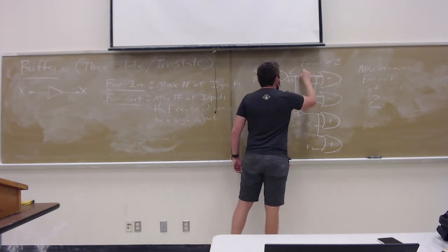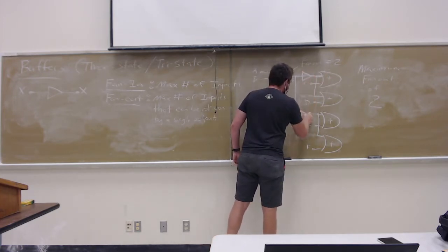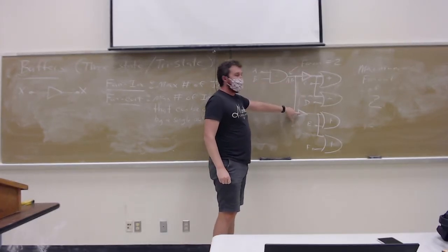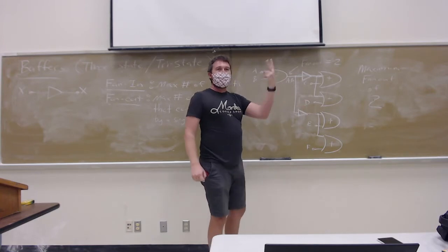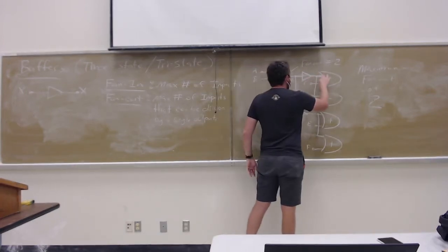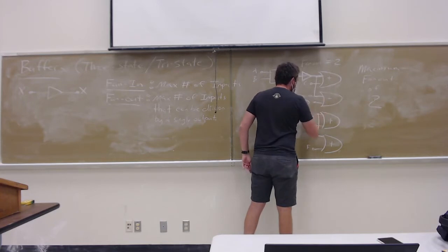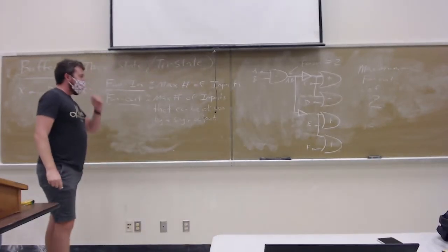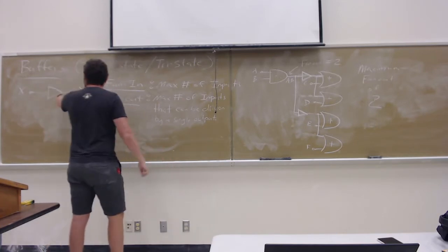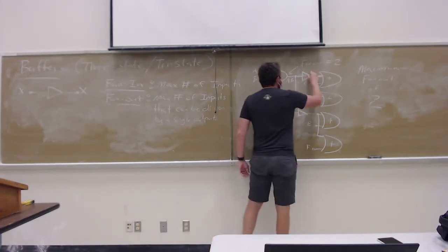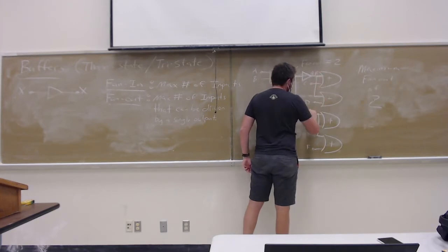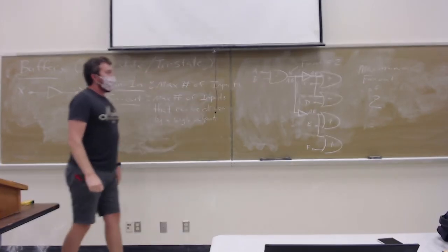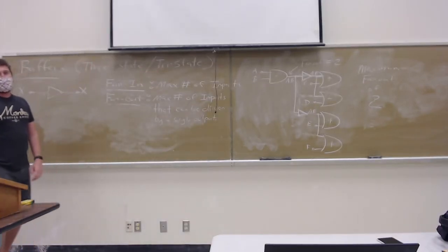Now this rule isn't being violated. The AND gate is only driving 2 gates. It's driving each of these buffers, and the buffers themselves can each drive 2 gates. And because it's a buffer, because the signal passes through, the output is still A and B. So the same logic expression is reaching all of the inputs, but we're not violating our fan-out constraint.